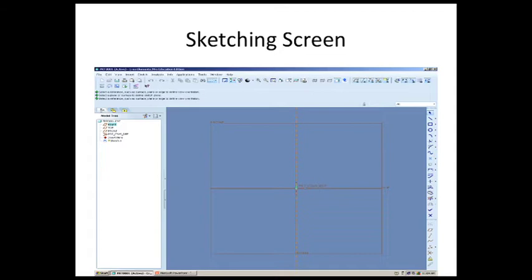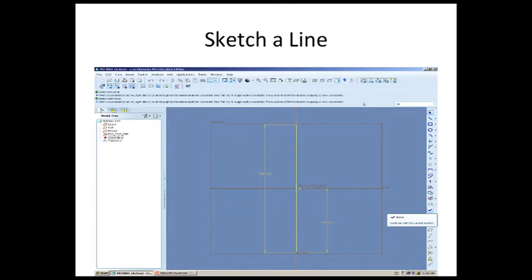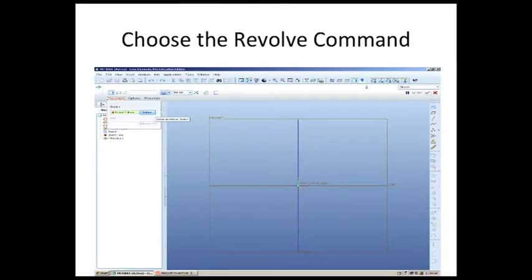From there, it will send you to your sketching plane, and that's where I'm going to draw a line right there in the middle. The length is 380, and halfway of 380 is 190, so it can be right in the center. The reason it's centered is for later on down the road. From there, you click the check mark, and you'll have a blue line in the middle. You really can't see it right now, but it's there.